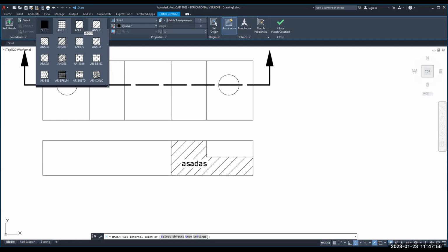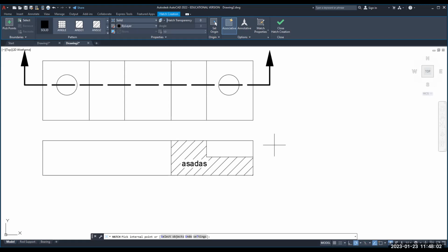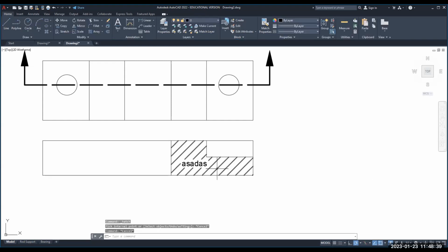That's the normal. You can change the angle. The reason we would do that is if this needed to be hatched, but it was like copper and this was like steel, you would use a different hatch pattern for a different material. Maybe not in metric. There's earth, there's gravel. I don't see it in the metric, but when you're in the US, you'll see specific hatch patterns. They've kind of gone away from it. It was really cool in the beginning, and then it became too complicated. Instead, now we just make them different for different materials, and then you'll call out the material.